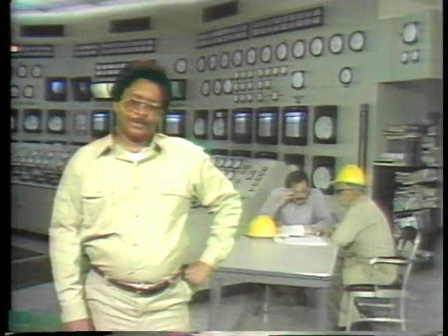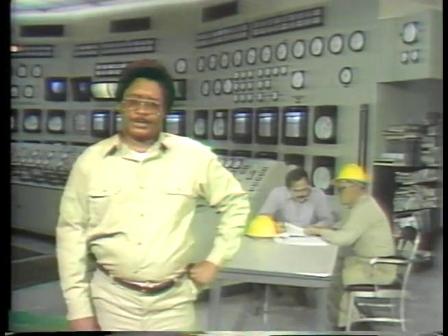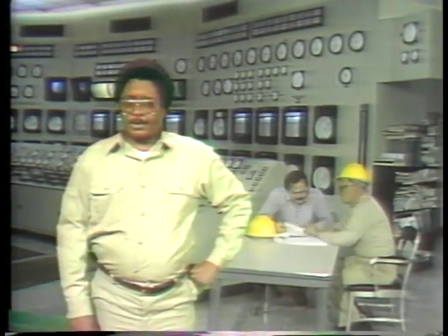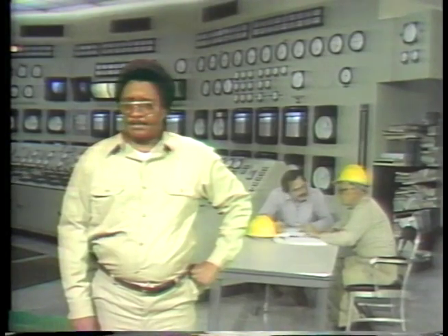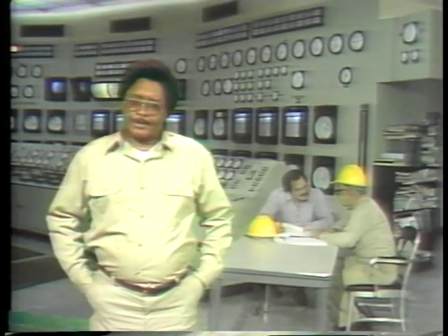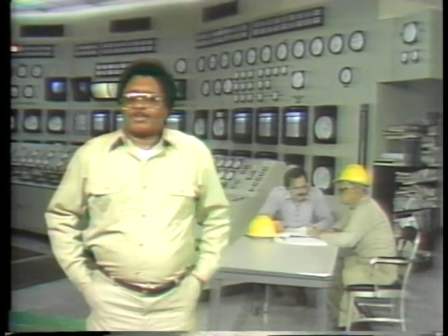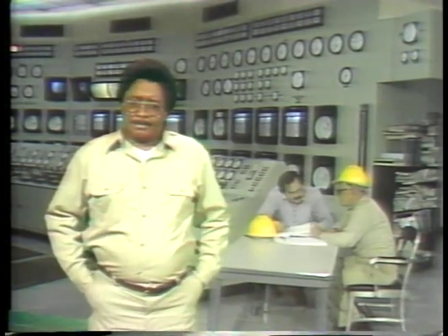So far in this unit, we've concentrated on Tables 1 and 2 of the steam tables, those that deal with saturated water and steam. You've also learned that close estimates of the properties of subcooled water can be found in these tables as well. The third table that we need to cover is Table 3, superheated steam. Table 3 gives you information about the properties of superheated steam, but it's organized differently than the tables we've looked at so far. We'll use atmospheric pressure as our example again.